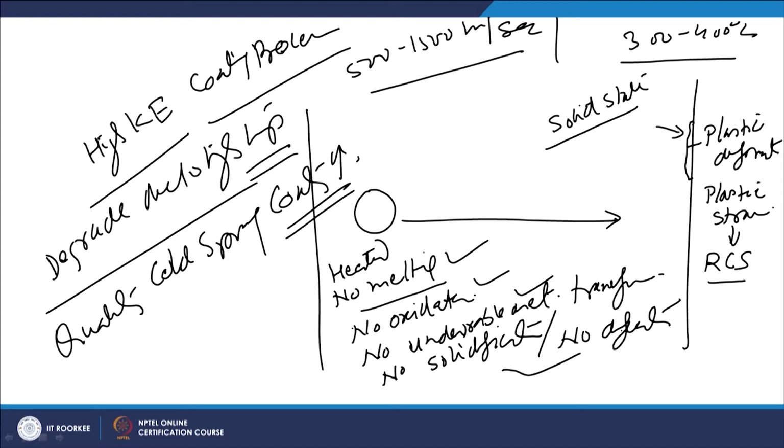In addition to this, we have one more advantage in this process. Whatever powder particles are being accelerated at a high velocity will get flattened after impact. So if they have any impurities or oxide layer on the surface, these brittle oxide layers, due to the plastic straining deformation after the impact, are broken down.